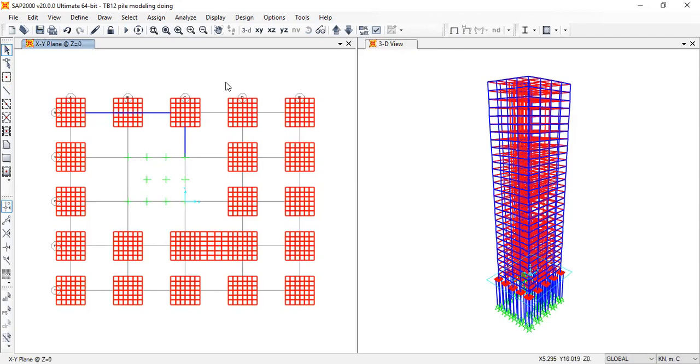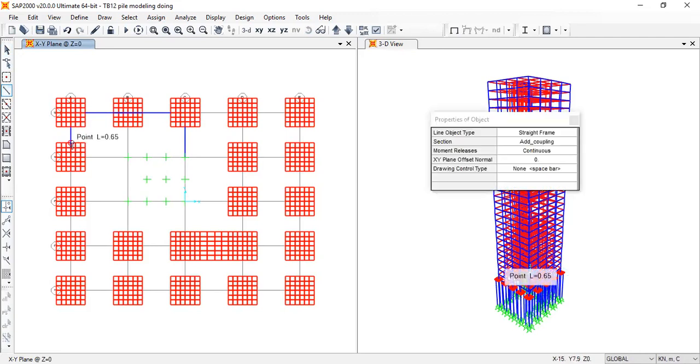And one last check is after you draw those things. So far we have removed the supports, but in the actual model we have soil here everywhere. So that structure cannot move, but this structure is unstable in that plane. So we have to make it stable.